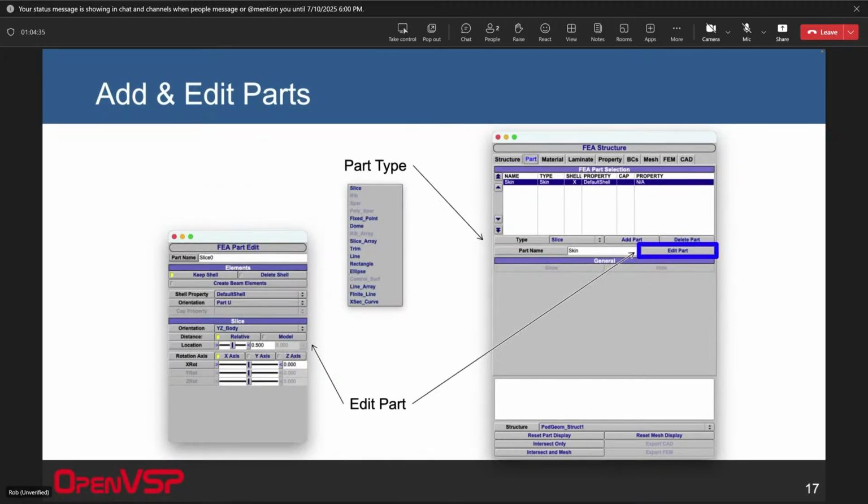Okay, so the second tab is the part tab. And here, when you're working on a structure, say the wing structure, this is where you add different parts. You add the ribs, you add the spars, or whatever else it is. You type in the part name that you want, and you choose the type from this pull-down list. There's a large number of types that you can use, and you click Add Part. Once you've added that part, it's added to this list.